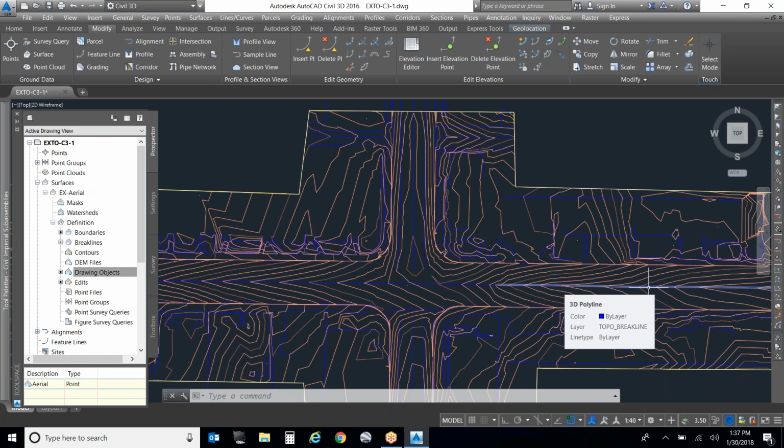Typically, your pipes cross the road perpendicularly, so you're only dealing with a typical 2% crossfall. If your pipe is skewed like this and you've got some grade on your road, the amount of cover from here to here is dramatic. So your pipe should be sloped to be an accurate representation. So don't just blindly assume that it's flat and that's accurate.